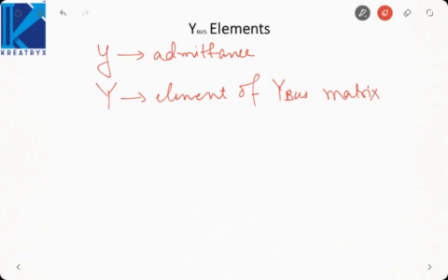So these two are the general notations. So if we write the equation in matrix form, it will be I1, I2 up to In. Here, these represent the current sources at each and every bus. So remember, if you are forming the nodal equations, then you have to convert each voltage source into a current source before forming the nodal equations.